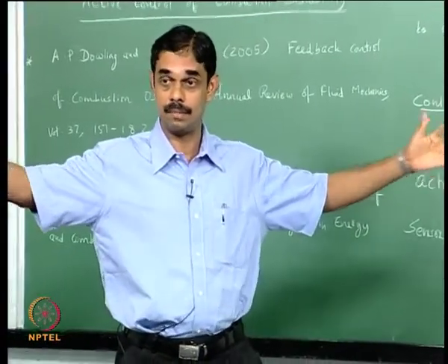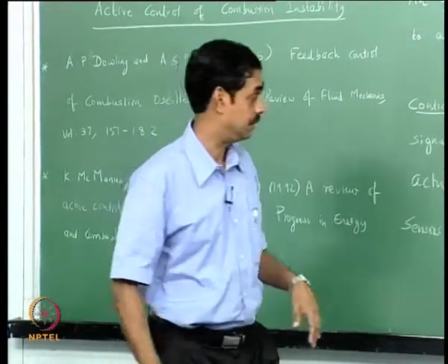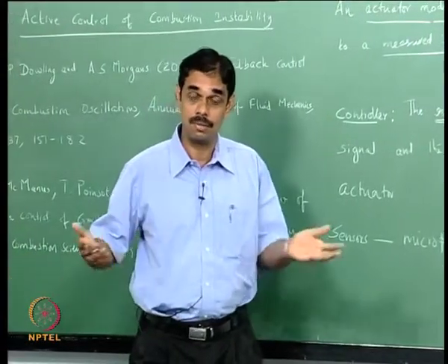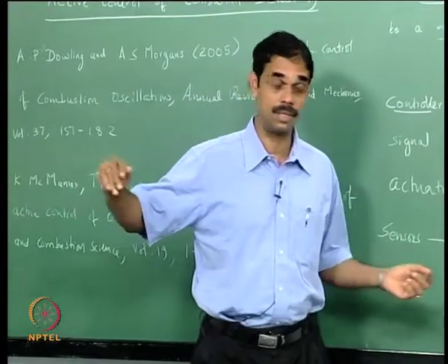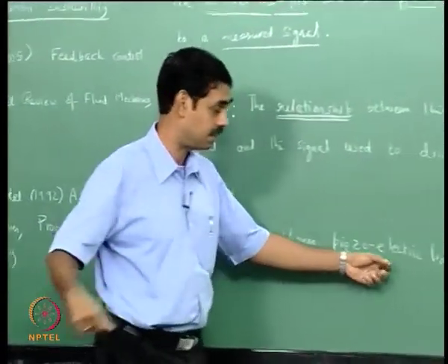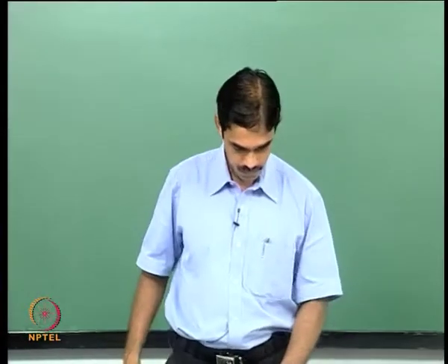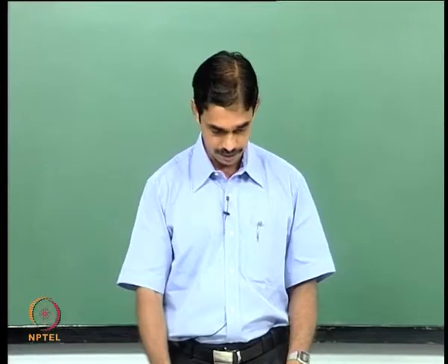We do not have any such problems because we get frequencies of the order of 50, 100 to several hundreds or 1000 hertz. So microphones or piezoelectric transducers both will work very well. The piezo transducers are roughly half to one third the price of the microphone.